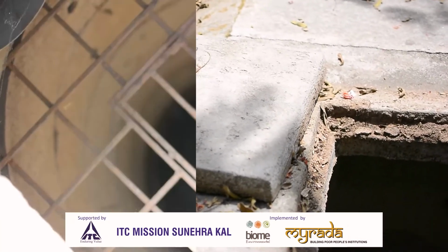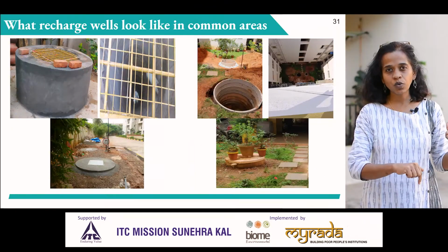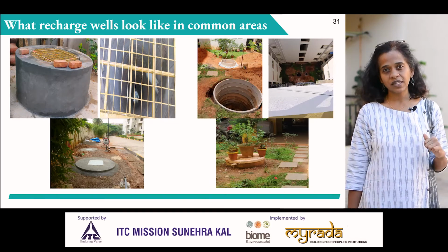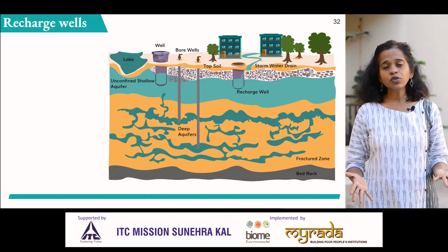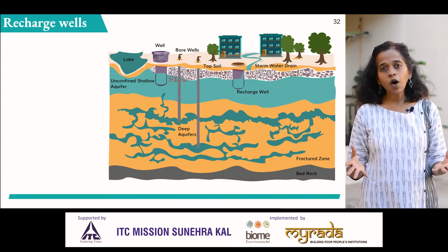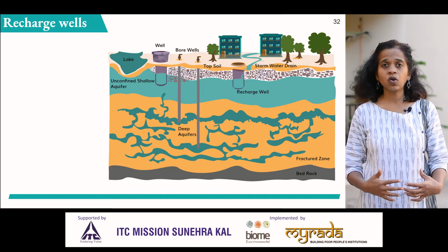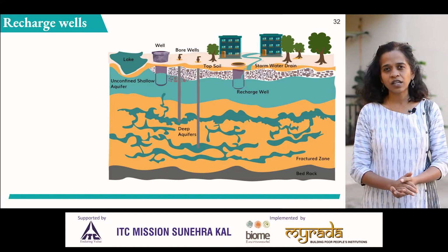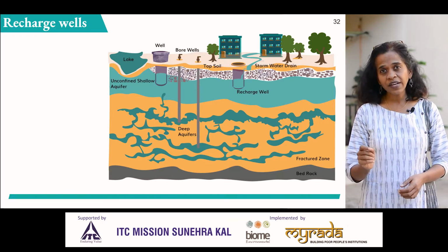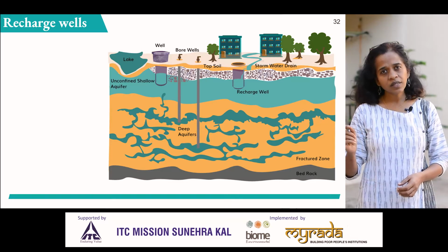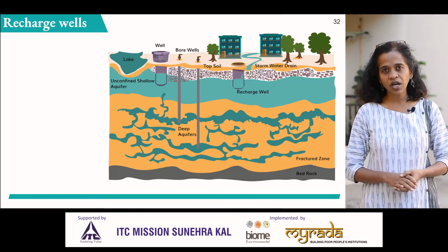Make sure there is a grill or some kind of access. It's always fun to look into the well to see how the water is going in, the rate at which it percolates into the ground. The point to think about is when we are putting water into the ground, how do we put it, how much and where, and how do we make sure that maybe it's coming back to us or it's at least available to the city at large. The simplest and most cost-effective structure, and that can be built with regular local skills, not requiring any expensive machinery, is the recharge wells.